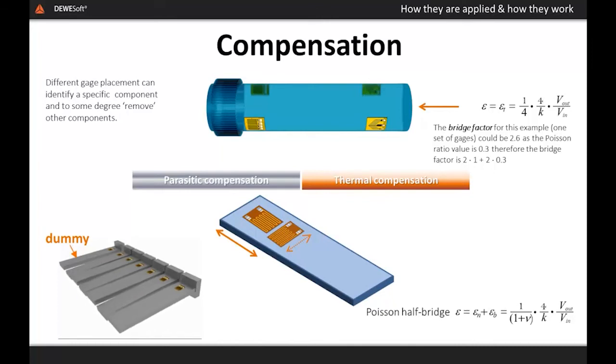As well as the single dummy component, you could dedicate a single channel as a reference point. In this case, a dummy specimen is instrumented and measured along with the measurement points. This is then mathematically subtracted from all of the other channels as the data is being recorded.